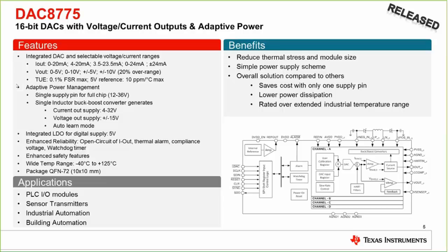So full tracking mode would completely react to any change in the desired output current, as well as any change in the load impedance. So barring some kind of compliance voltage condition, if you were to try to drive a load that's too big or drive too much current into a large load, you'll always see the desired output current across the load.